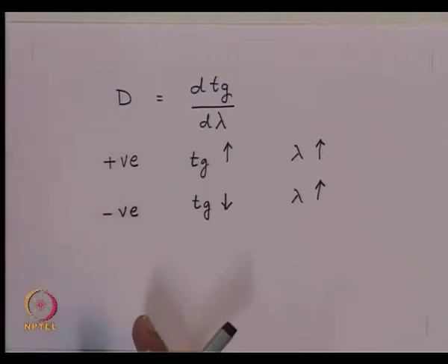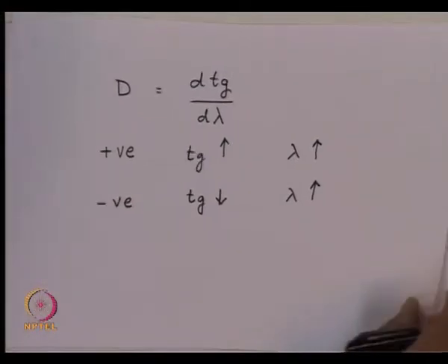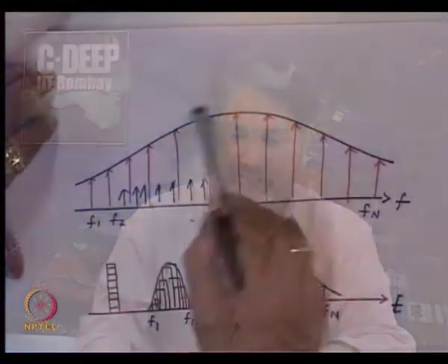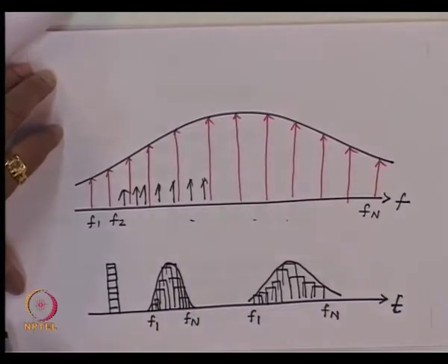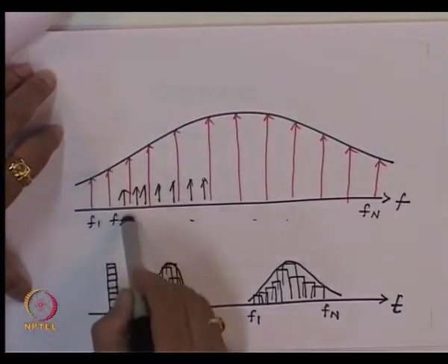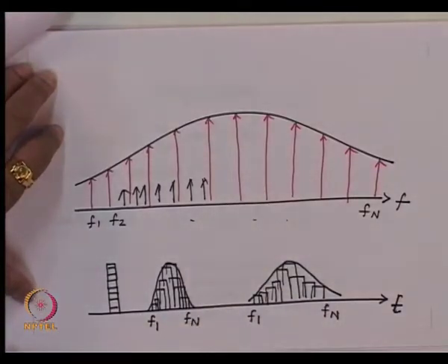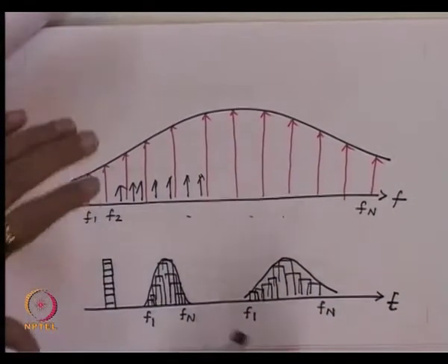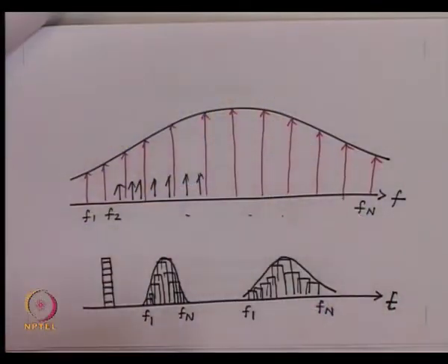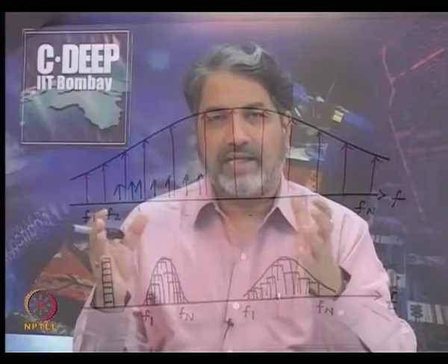Now you recall, when we talked about the dispersion, we said that the phenomena can be visualized as transmission of multiple signals propagating on the optical fiber. So you have this wide spectrum of your source carrier, and these are the different components which are present in the carrier. And we said the scenario of propagation can be visualized as the pulse is riding on each of these carriers and reach on the other side, and the total thing what you see is again a combination of the different pulses which have traveled on different carriers.